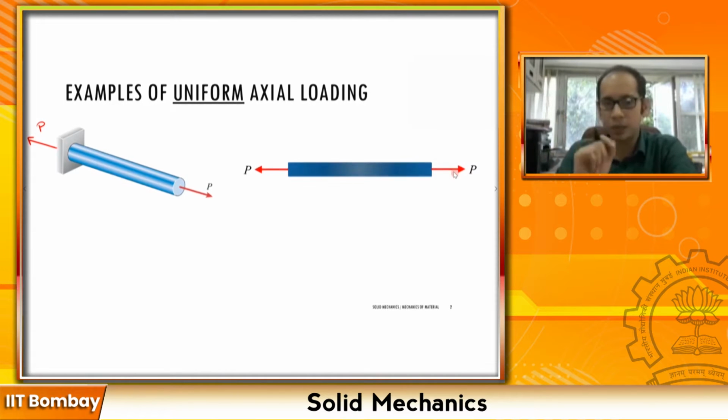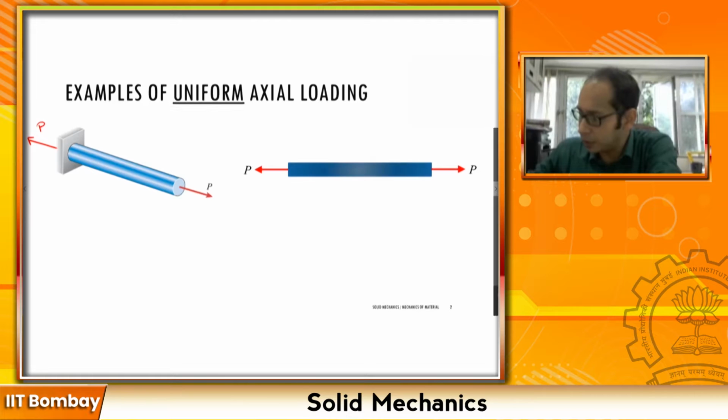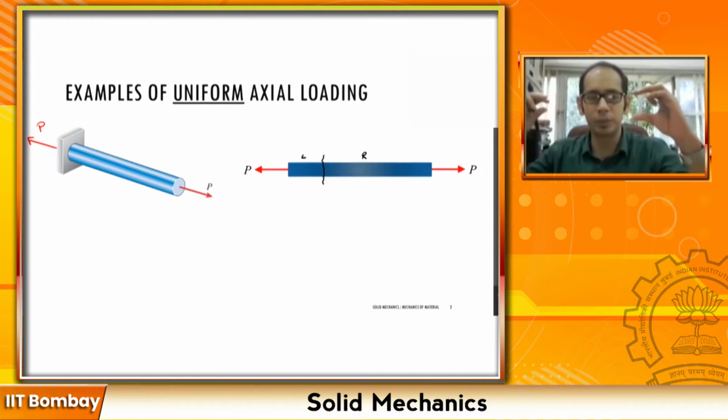Now let's look at these internal stresses we have been talking about. If I take this bar and break it into 2 components, by taking a particular section somewhere around here, with this as my left end and this as my right end, then remember the whole bar is in equilibrium, so the individual parts must also be in equilibrium.